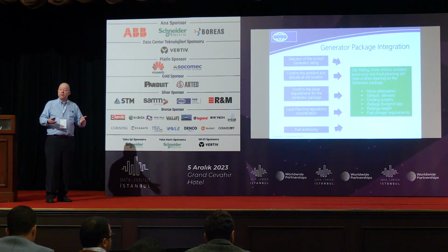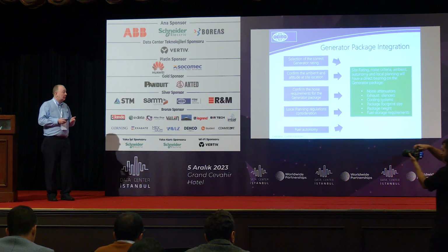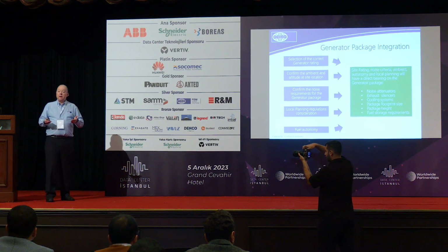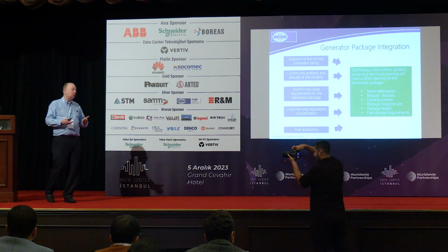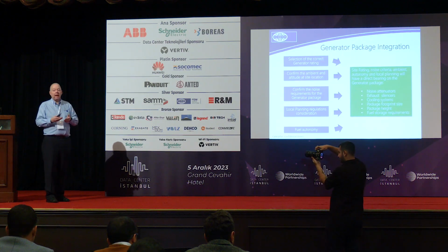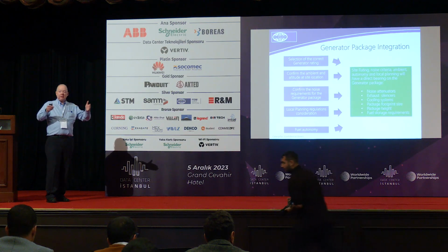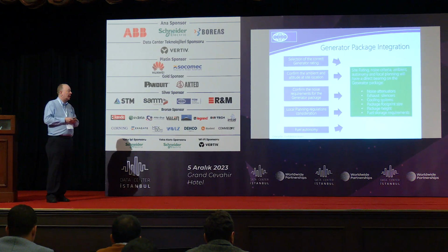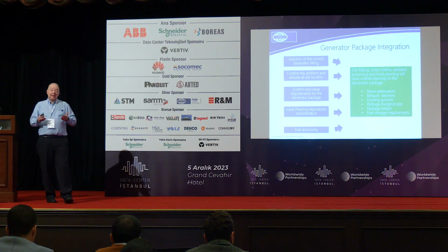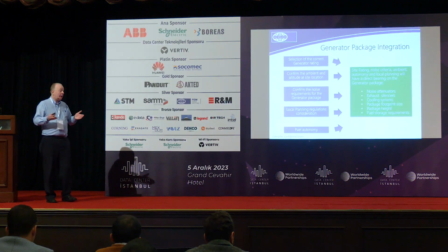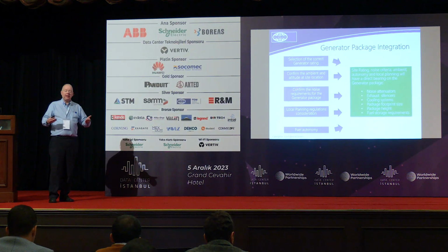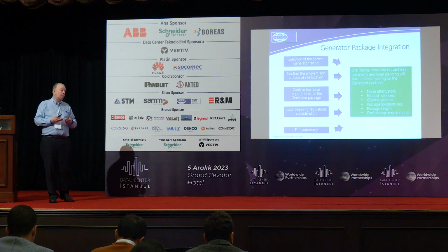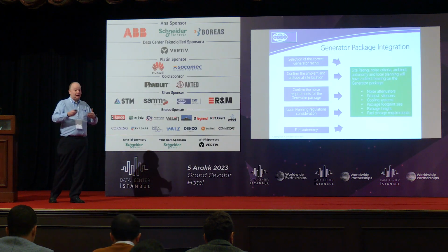There may be very specific noise requirements that the site needs to deal with, and there might be planning regulations around that. There might be sightline or exhaust stack height limitations for your actual data center. So in that situation, we need to size the genset, and if you have a very tight noise requirement, that will almost certainly make your package bigger. So you have to take that into consideration in relation to your overall package design.